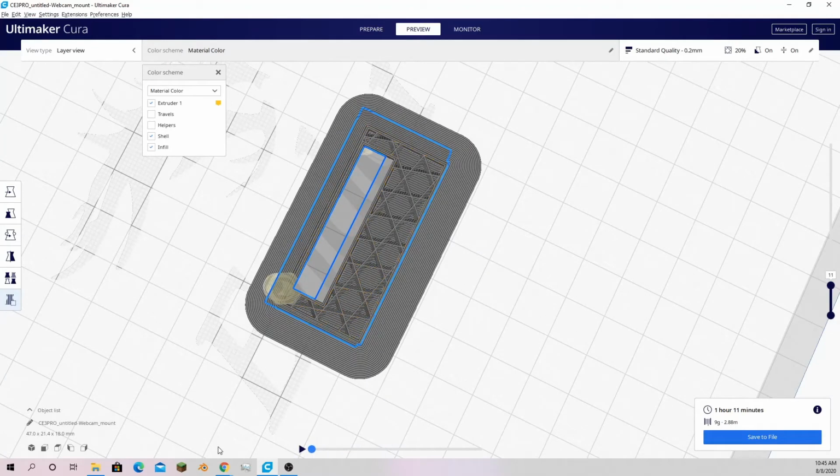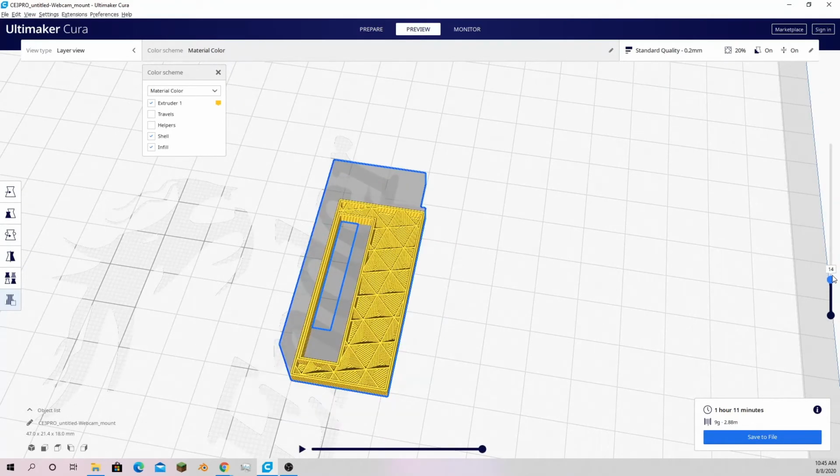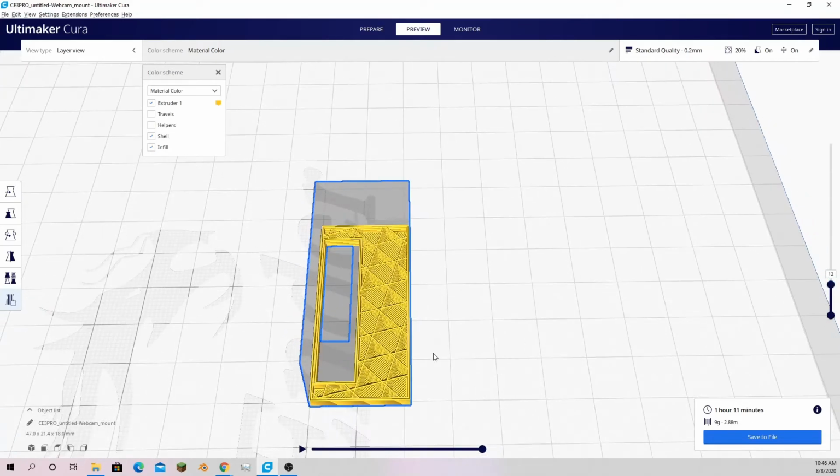Now, when you're 3D printing, these are what we have to focus on: the infill and the wall supports. The infill right here, this is cubic, which is the pattern. It's a three-dimensional pattern, meaning instead of just being a pattern like a honeycomb that prints a honeycomb and puts the layers on top of each other, it moves in three-dimensional space, which adds a little bit more structural integrity. So I also set it at 20% because this isn't that structurally strong. It doesn't need to be.